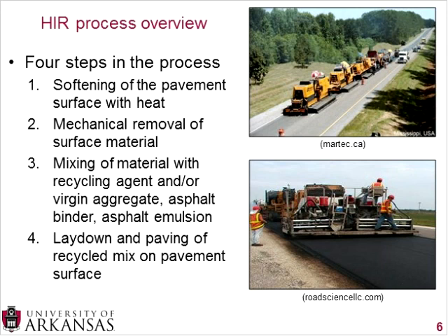And once you've heated it, you somehow mechanically remove that heated surface material. And you can do that either by scarifying the surface, which we'll see in a couple of slides, or you can actually use a mill of sorts and mill that material up. But the benefit is that it is at a higher temperature, so then you can add things like recycling agents or even a little bit of virgin aggregate, asphalt binder, or asphalt emulsion.